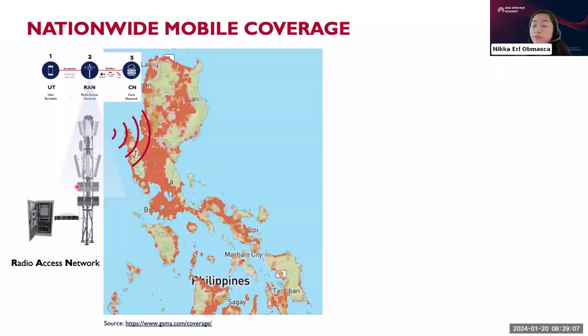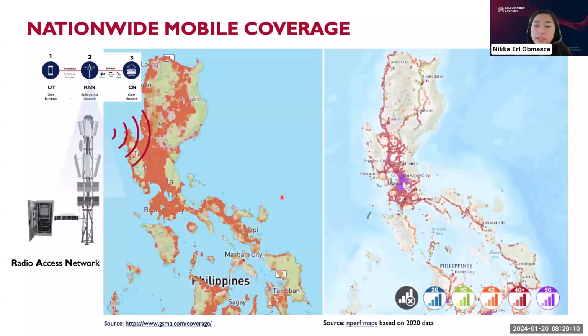When planning the deployment of the RAN, the engineers, network operators, telecom providers, and network designers really consider a lot of factors when planning where to put these cell sites. Here, there are a lot of cell sites around the Philippines. Examples of these factors are population density, topography, building density, and traffic patterns within a coverage area for us to stay connected.